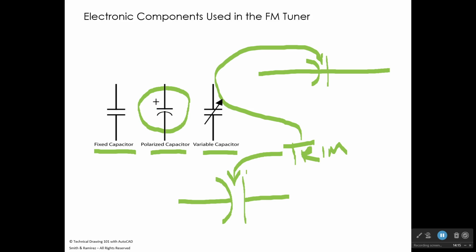When you look at the sketch of the schematic on page 380, you're going to see that the capacitors are put in there with an orientation, and you need to make sure that you rotate or mirror or whatever you need to do to that capacitor to get the orientation correct in the schematic.